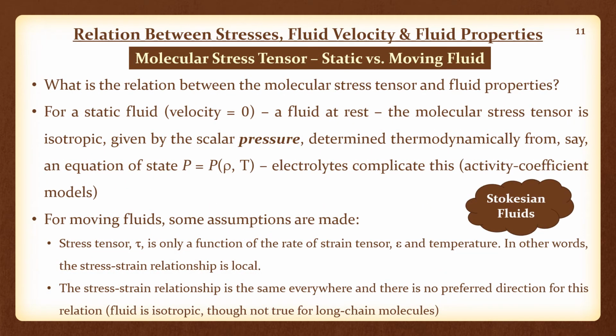So with this picture of velocity gradient, rate of strain, and vorticity, now we have looked at what happens to the fluid. What are the motions that are possible when you are subjecting a fluid to some sort of contact stress? That could be either a deformation or a rigid rotation.